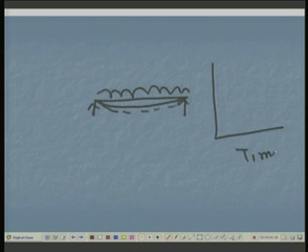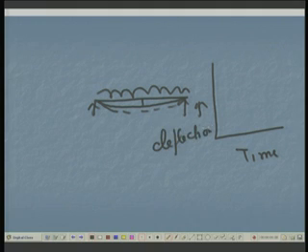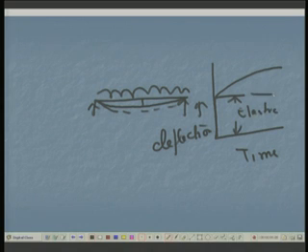That means, if I plot time on the x axis and the maximum deformation, let us say maximum deflection, on this side, I will find that instantaneously it will show some deformation, and with time there will be some increase. So, this is elastic deformation, and this is creep. We may not have time to look into the details of creep, but this is the creep deformation. This happens in the case of concrete creep.